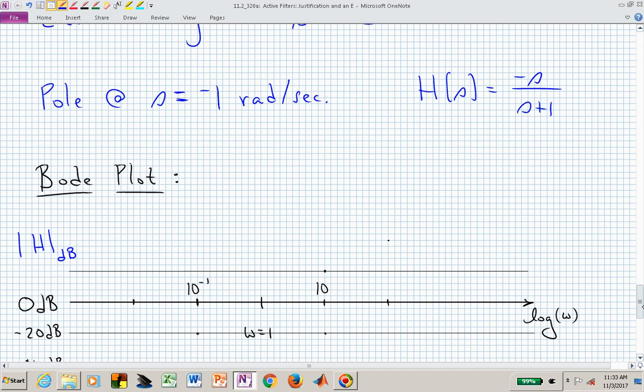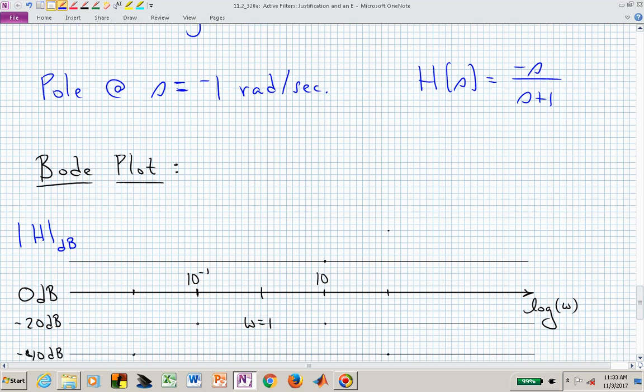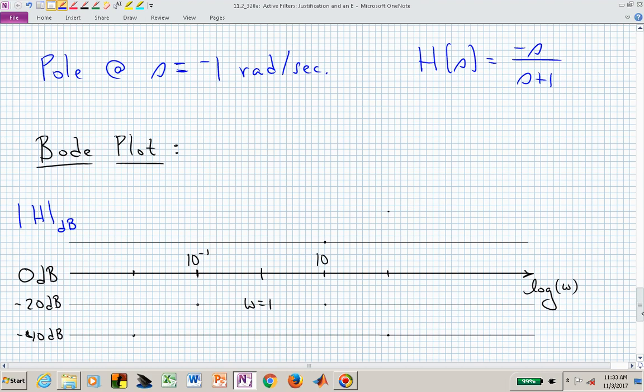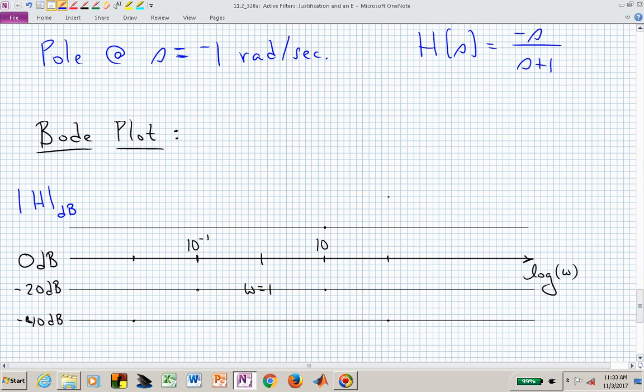Let's just go ahead, as a sort of review, and sketch what that looks like. And if we sketch the magnitude, we don't have to worry about that minus sign in the magnitude response. We have a 0 at the origin, which now says, oh, it's always sloping. It's upstairs, so we have a positive slope, and it's going up at 20 dB per decade. So let's now see.